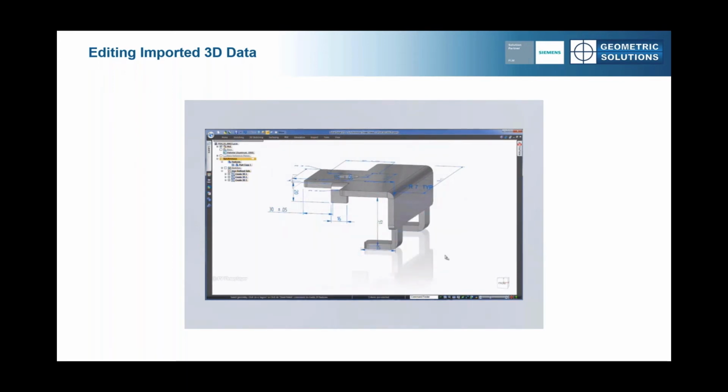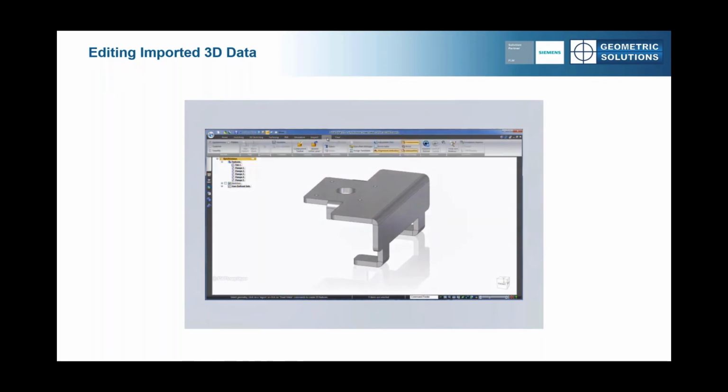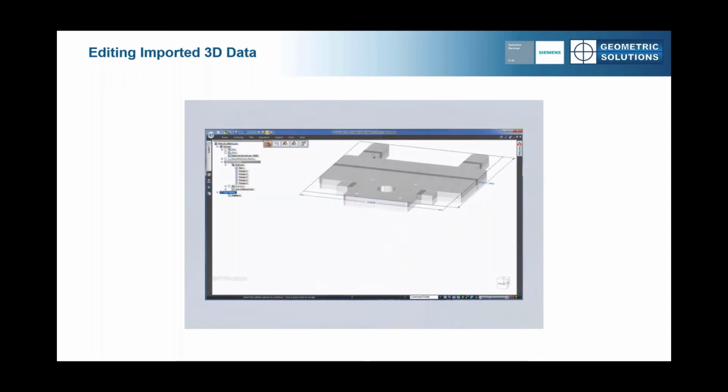For manufacture, we do need a flat pattern, but because this part wasn't created in Solid Edge, how are we supposed to produce this? Go back to the supplier? No, not a problem. We can tell Solid Edge to treat this as a true sheet metal part, flanges and all. Now we have an instant and accurate flat pattern.